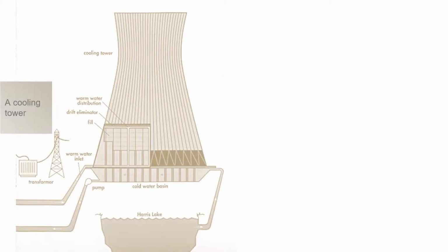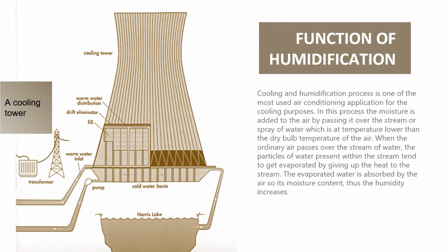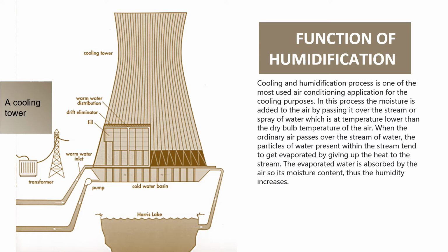And now, we want to know the function of humidification. What is actually the function of humidification? Cooling and humidification is one of the most used air conditioning applications for cooling purposes. In this process, moisture is added to the air by passing it over a stream or spray of water, which is at a temperature lower than the dry bulb temperature of the air.